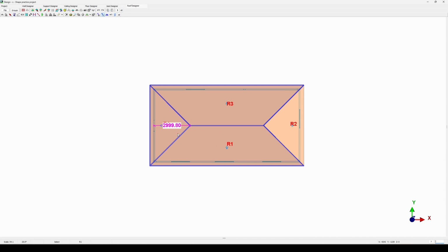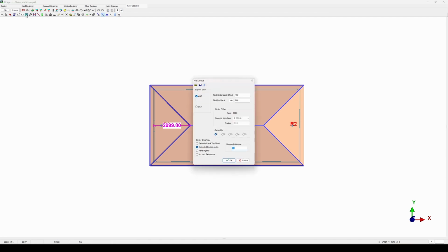After completing the selection, we're going to see that this tool right there gets activated. Without having this correctly selected, in this case, we'll do a reset on the selection. If we do the selection incorrectly like this, you'll notice that this tool does not get activated. So please make sure that you start with the triangular part, in this case the hip side first, then the two sides right there, and then we get to the Auto Hip Set tool and we'll click on that.